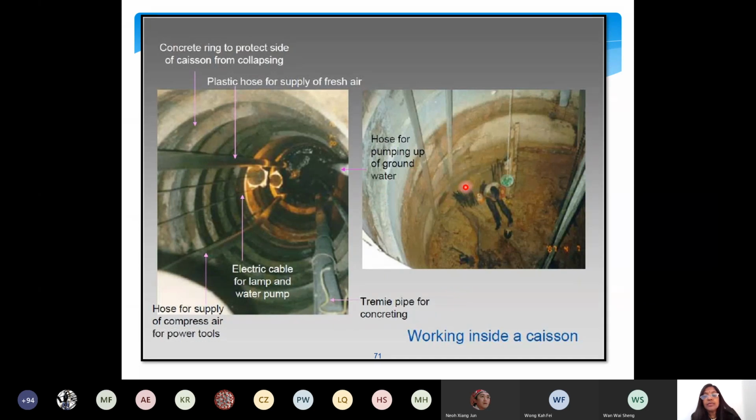After construction, they found that water is coming out. They have to remove it. If it is from a continuous supply of water, a continuous aquifer, like what we call a confined aquifer, then you should avoid this place. You should really close it back. If it is a small layer of water or intermittent water, a small parcel of water, you can pump it out and continue your digging. It's all given by the borehole test. The strata will be studied, and based on that you can get advice for further construction.